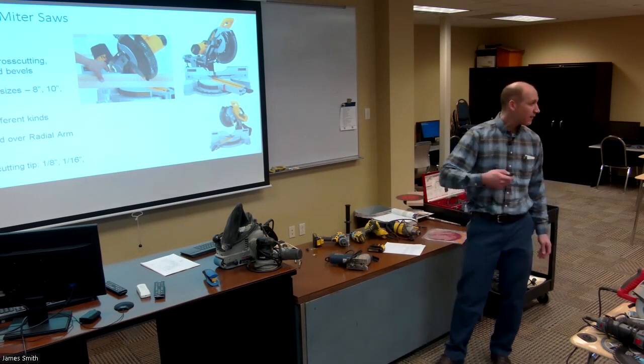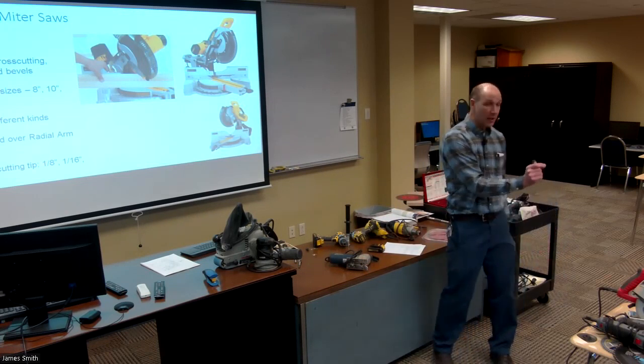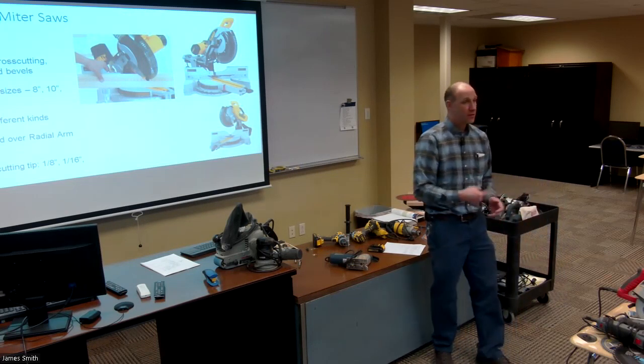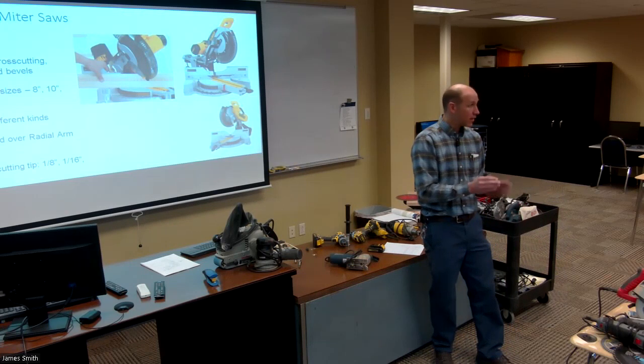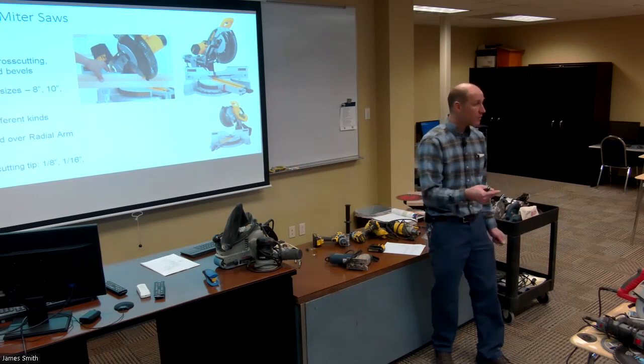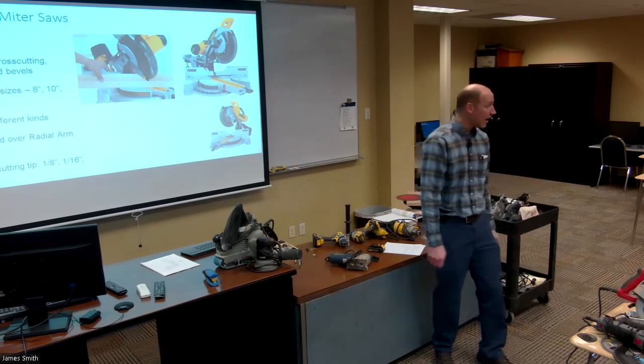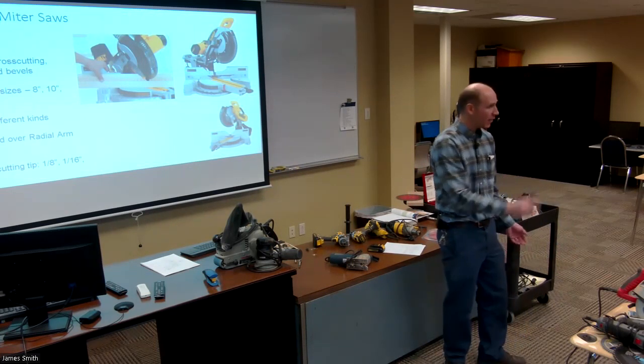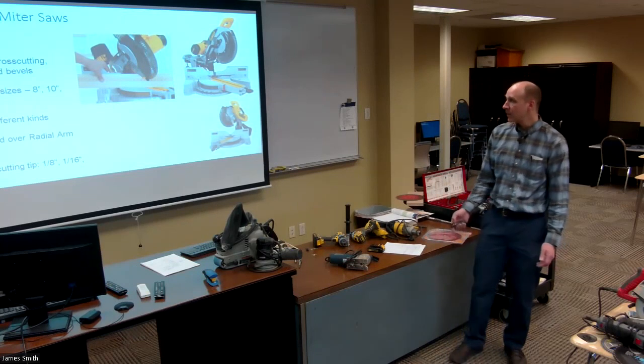And then if you need to take off an 1/8 inch, that's about the width of the blade. If you want to take off a 1/16 of an inch, that's half the width of the blade. And so the blade is a great reference for removing material without necessarily laying out on the board, because oftentimes you just need to take off a little bit and you can't really lay that out very well anyway. So